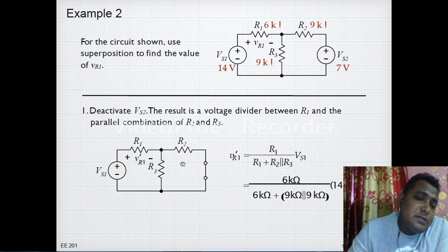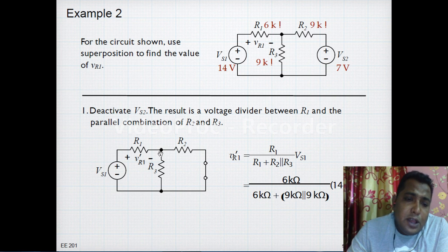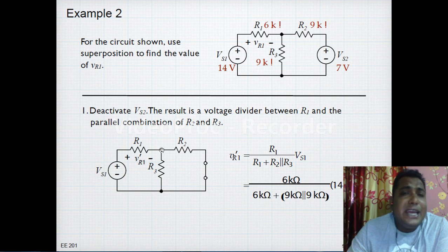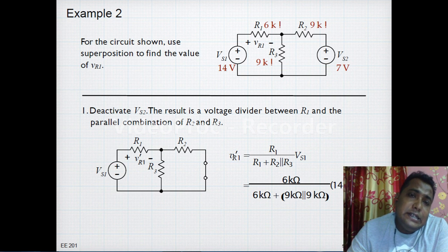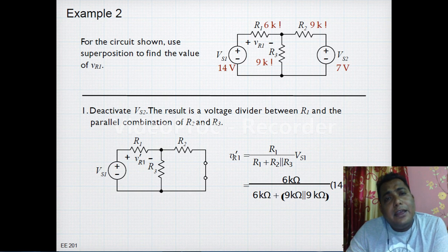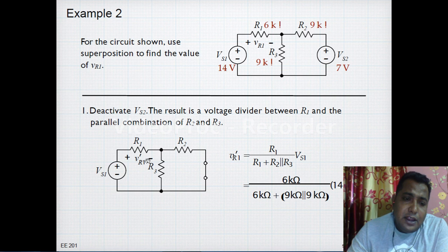So what is the series parallel combination of resistance? At this node, the source current is divided between R2 and R3. So we can definitely say that R2 and R3 are in parallel, with R1 in series. This is the equivalent resistance we have.